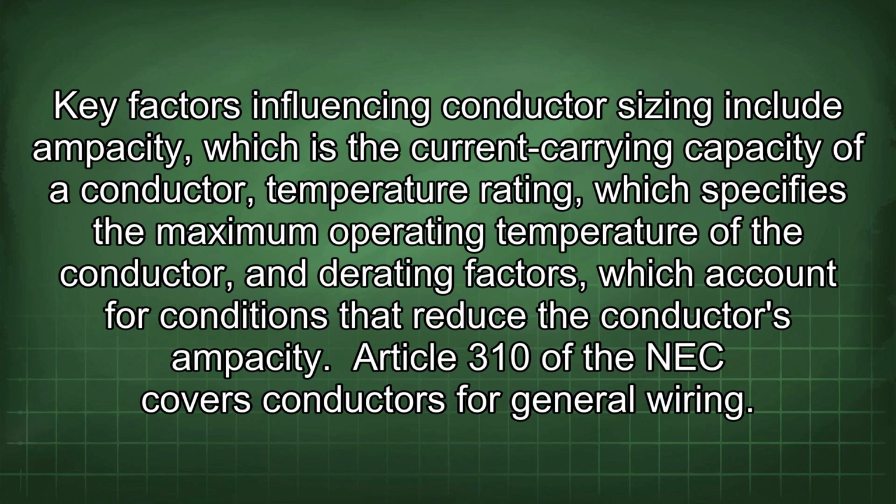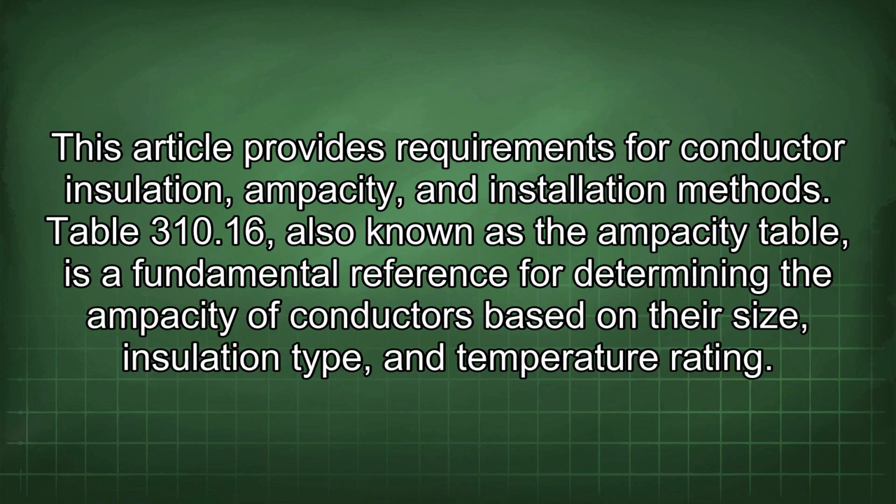Article 310 of the NEC covers conductors for general wiring. This article provides requirements for conductor insulation, ampacity, and installation methods. Table 310.16, also known as the ampacity table, is a fundamental reference for determining the ampacity of conductors based on their size, insulation type, and temperature rating.